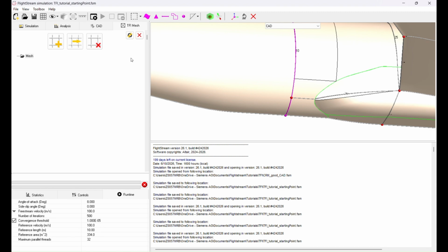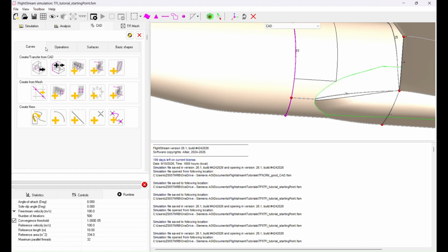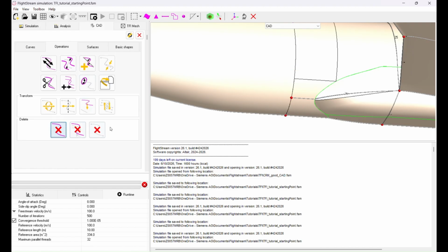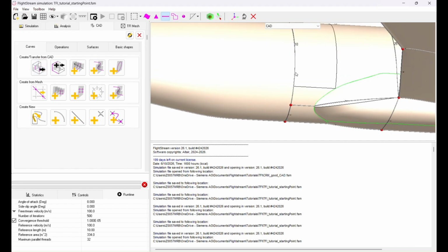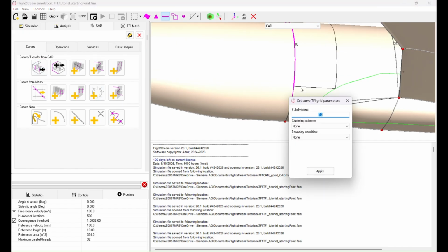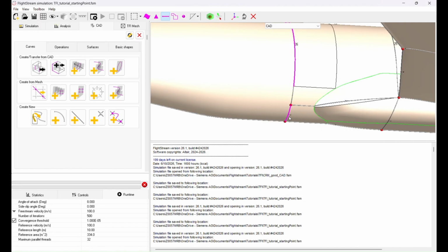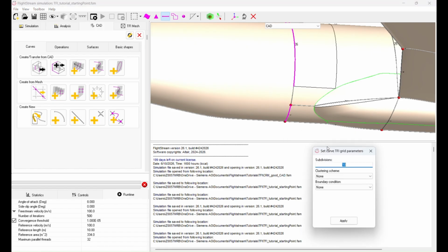Here we notice that this curve isn't properly split, so we're going to delete it and recreate it one more time. In the proper structure for our panel shapes. With that done, we can change the number of points appropriately. This becomes 26 because we need to also deal with the blunt trailing edge on the rear of the wing. This will normally go to 15.